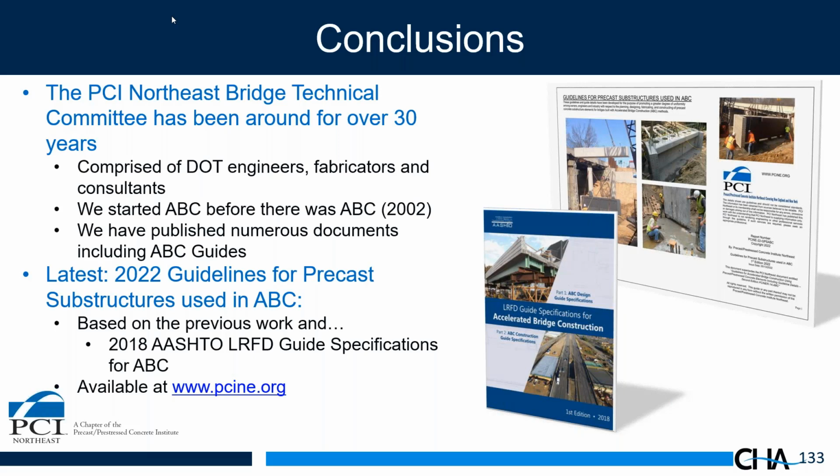Okay. And finally, what is the cost difference of cast in place concrete substructures compared to precast concrete substructures? Well, I hope with these new details, the price is going to come down and they're going to be very cost effective. But there is one element that I am confident is less expensive with precast than cast in place, and that would be pier caps. I always tell people, if you want to dabble in the world of ABC substructures, start with a precast pier cap. Pier caps with cast in place, think about it.